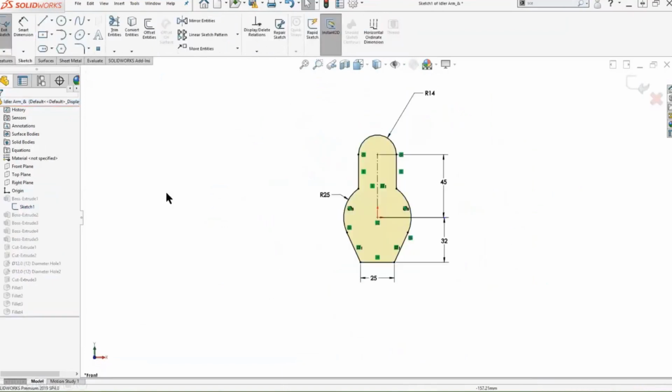Same is true with editing any existing sketch. So again, take a look at those options. Maybe just remember auto normal to. You could search for it. It's one of the first tips we looked at here. And maybe you want to set your SOLIDWORKS session to automatically go normal to any sketch you create or edit.